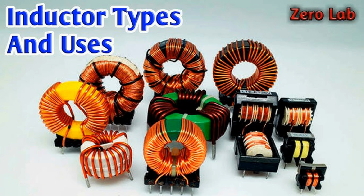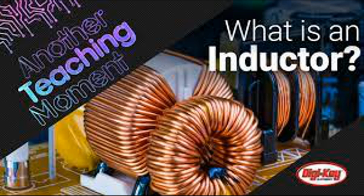Power transmission. Application. Transformers are used in power grids to transfer electrical energy from power plants to homes and businesses. High-voltage transformers step up the voltage for long-distance transmission, minimizing energy losses. At the receiving end, step-down transformers reduce the voltage to safe levels for household and commercial use. Example: high-voltage transformers are used in substations to step up the voltage for transmission over long distances, reducing energy loss in the power lines. Electrical isolation.